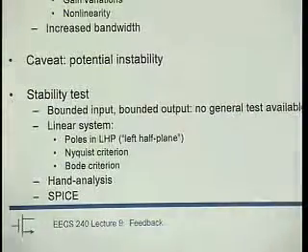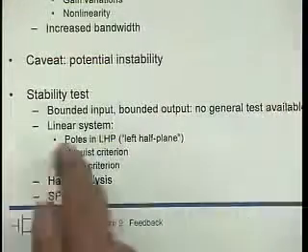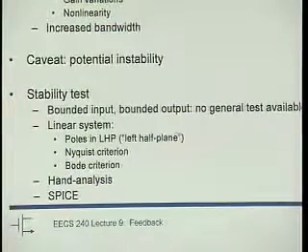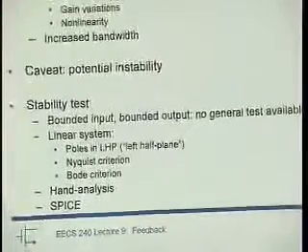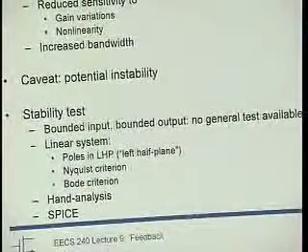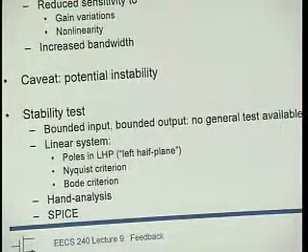And I can give you circuits, nastily enough, but they're good circuits, where you can do this linear system analysis, and lo and behold, it's stable, and then in reality it's not, because it's a nonlinear circuit. Class AB amplifier, typical case. Or circuits that need to be powered up, right? Because during the power on transient, it goes through all sorts of states. It can start ringing long before it reaches the steady state, and it will never come on the way you'd like it. Okay.